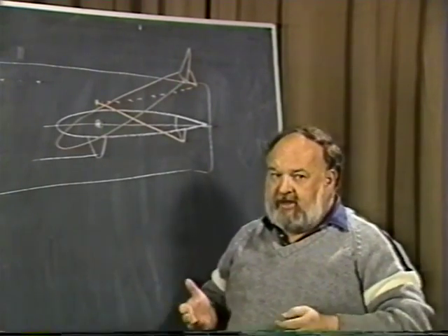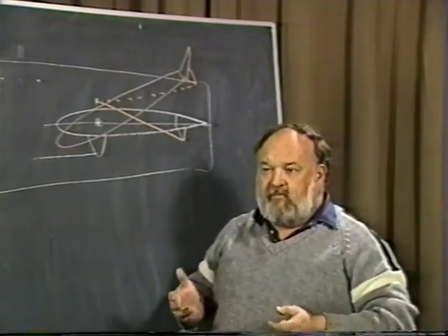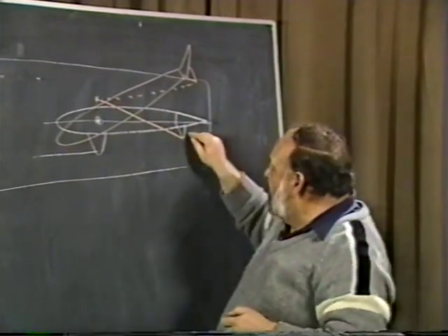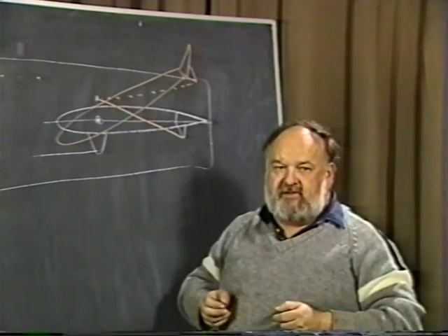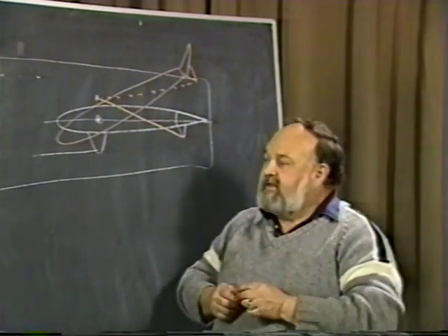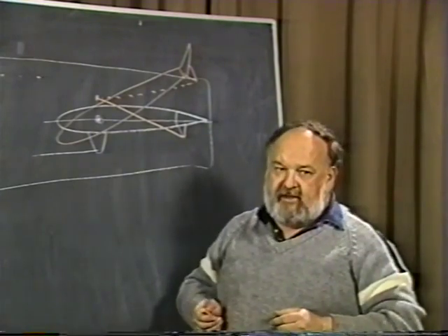And you can actually build the airplane and get it flying, and once you're flying, you say, wow, the elevator is too heavy. No problem at all. You go back there, almost drill different holes, and you can find new positions on your linkage, and linkage alone, and dial in the kind of stick force you want. This is the real nice part about an all-flying tail.